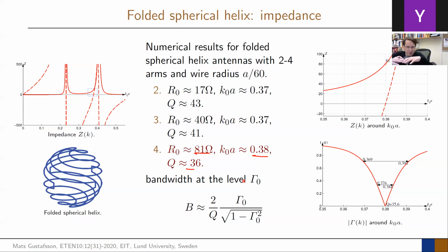So now you can start tuning with this, and you can actually design an antenna if you would like to, which is in some ways 50 ohms. And it has a very small electrical size. And actually, these antennas are performing according to what physics says you can do. They are optimal for their shape, very close to optimal. So they cannot in some ways be improved, but in most cases, we are not interested in a spherical shape.